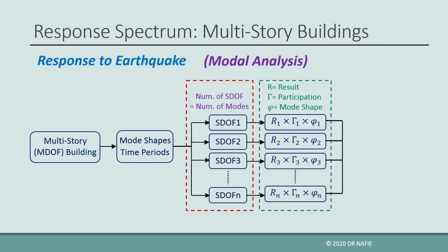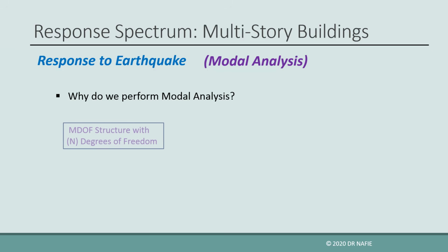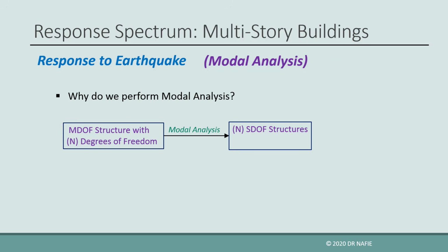The final response of the building is obtained by adding the responses of all the mode shapes. So, what are the benefits of modal analysis, and why do we want to use it in the first place? Because the modal analysis is changing the multi-degrees of freedom into several single degree of freedom systems, then we can benefit from all the advantages of the single degree of freedom analysis.